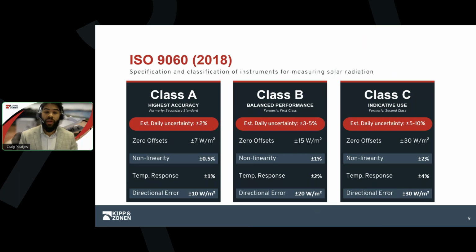Each of these operational guardrails also contributes to the overall measurement uncertainty of the device. There are a few key things to mention about overall uncertainty. There is the calibration uncertainty of roughly 1.2%, which is also governed by the ISO standard and forms part of the total estimated uncertainty. The rest of the components of this total estimated uncertainty is determined by real-world operating conditions.